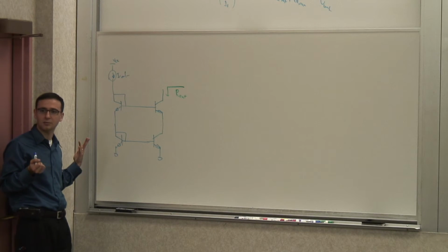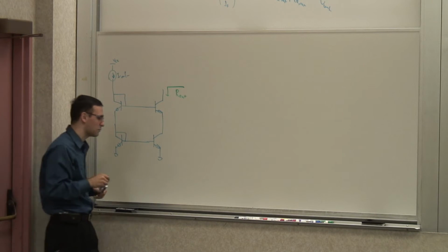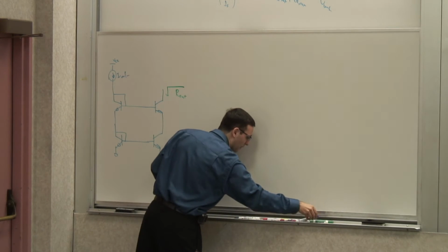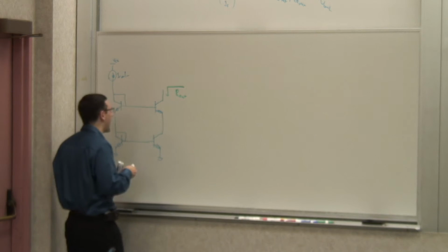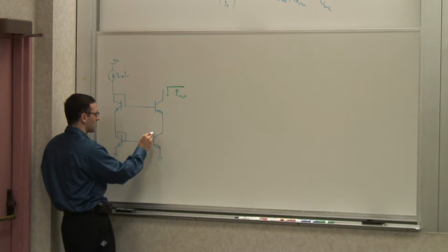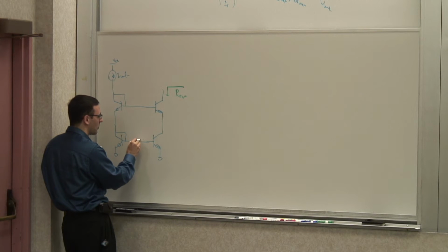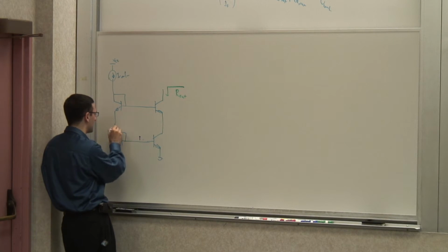Right? Because the cascode now will give some cascode beta RO. But now there's an interesting thing in this stage. Because of this base current in RE, what happens is there's a second signal path through here. So a variation here, right? So let's say you change this node a little bit. You push it up a little bit. This node is the same node. They're shorted. This goes up a little bit. This goes up a little bit.